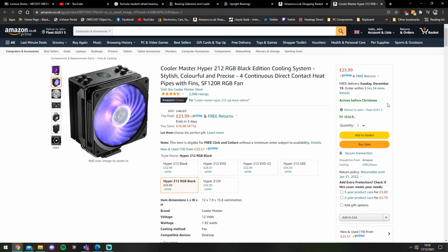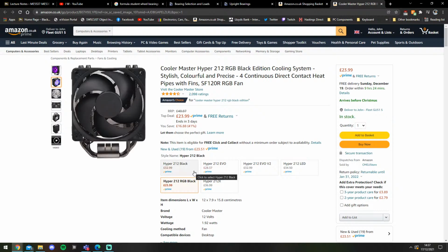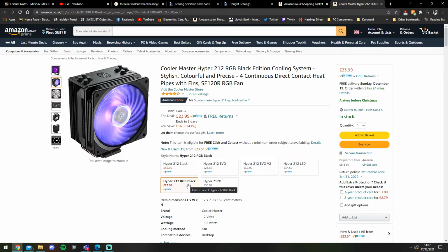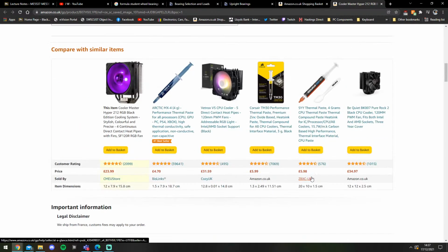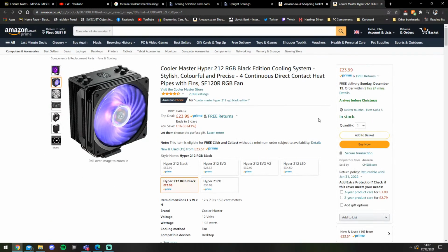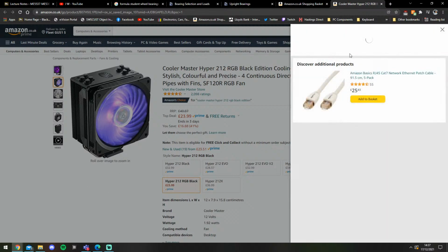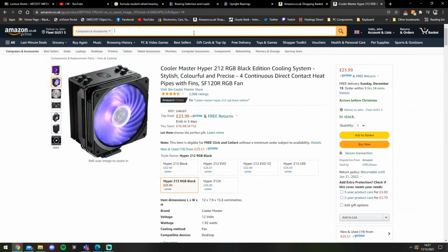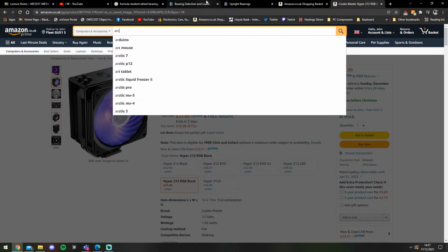After passing through the radiators, the air must again leave them accordingly. And when idling, there might be the risk of circulating air, as described here, marked with the A, and additional backflows as shown by the figures B and C. So there might be a risk of heat accumulation, which must be avoided by a proper ventilation of the coolant air. And this can be achieved by using a fan.